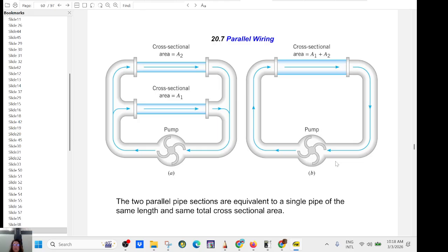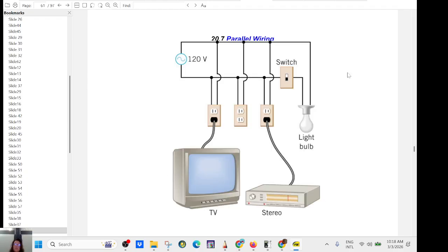If you have a circuit in parallel, you're going to drain more current from the power supply. That's what we use in a house. If you have 120 volt from the outlet, all the loads will be in parallel, so all the loads will have a voltage drop of 120 volt, and they're not complaining. How much current flows through each load depends on their appetite, on the resistance. So they get what they want.